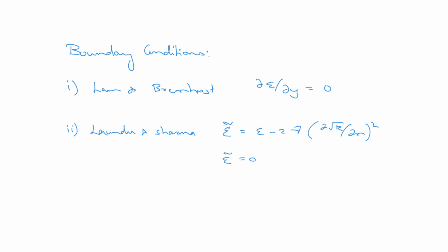Also epsilon tilde equal to 0 can be allowed to be used. And we should also note that these boundary conditions will make the problem numerically stiff. Also, if we use this nonlinear wall damping function, we will encounter difficulties in achieving convergence for the simulations. So we should note these problems and, based on that, properly utilize these conditions in the application.